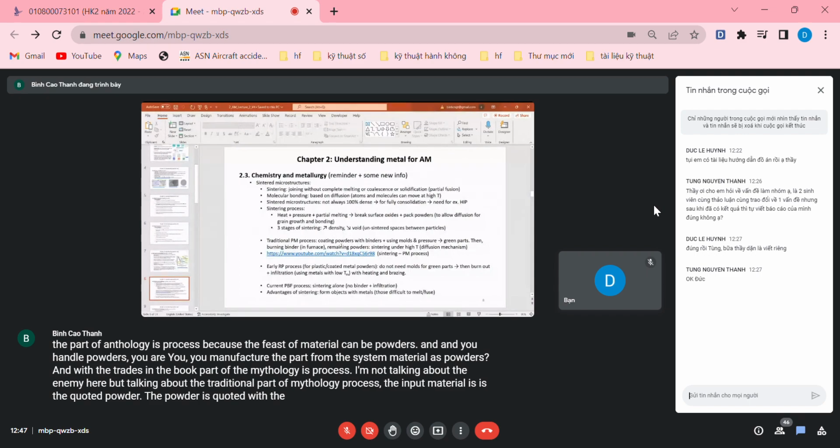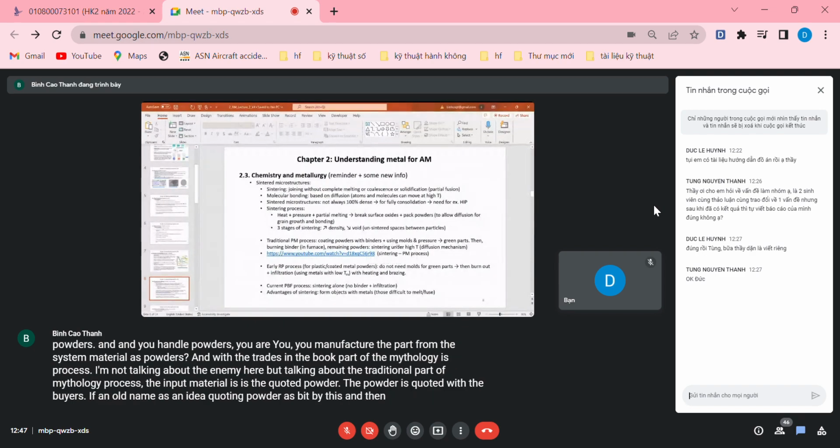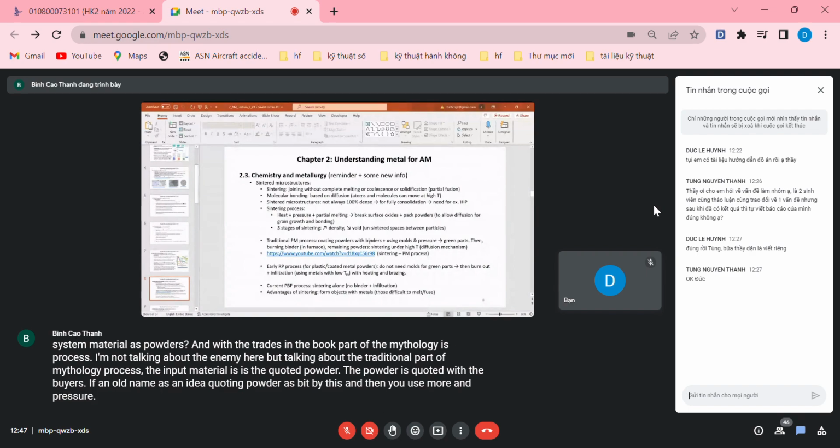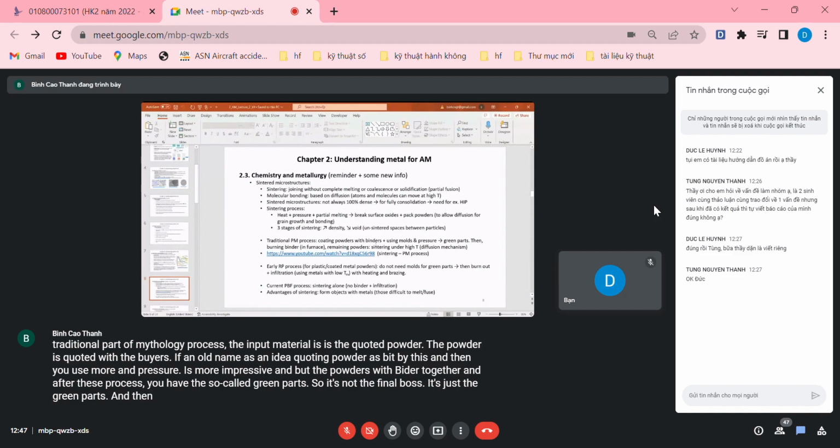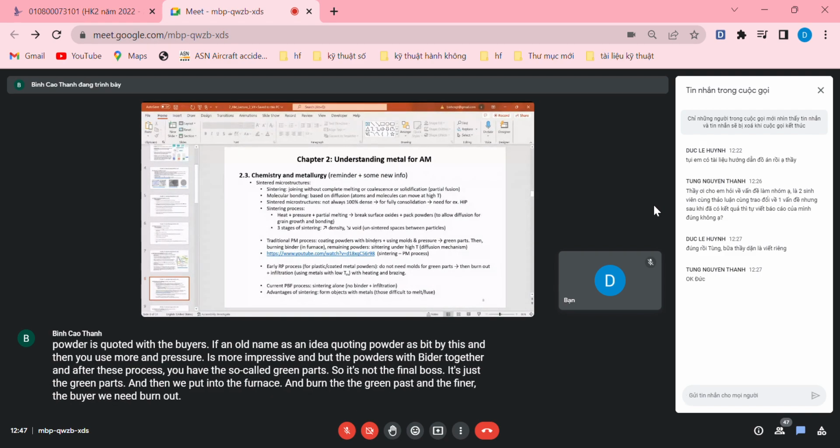Cái vật liệu là bằng bột này nó sẽ được phủ bên ngoài bởi các cái chất tinh kết. Coating powders with binders. And then people use a mold and pressure, and pack the powders with binder together. After this process, you have the so-called green parts. So it's not the final parts, it's just the green parts. Then we put them into the furnace and burn the green parts, and the binder will be burned out.